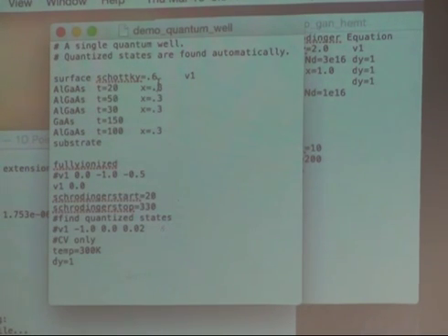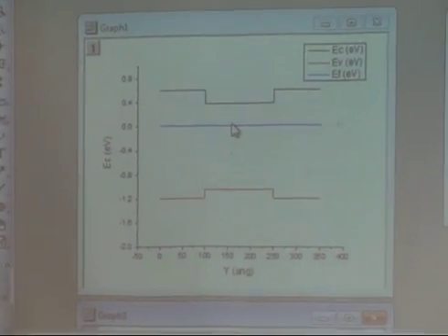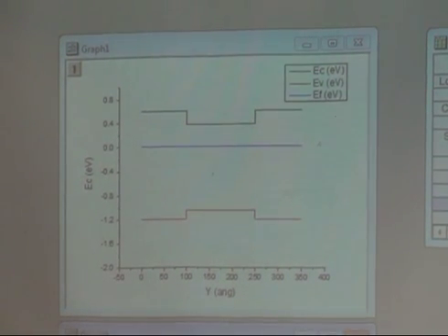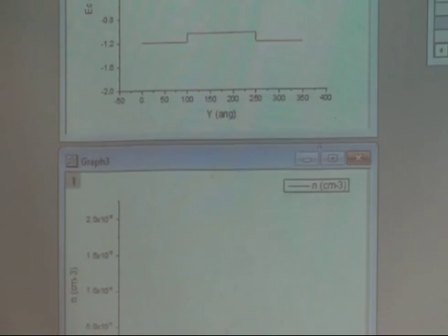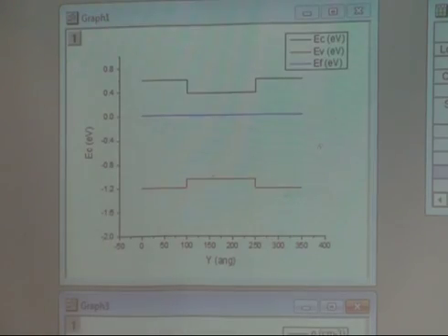What I'm going to do is populate that quantum well with electrons. Right now, you look at this structure, there are very few electrons in the quantum well. I mean, there are some, of course, but they're exponentially small, and the carrier density is very low. Right? I want to put electron gas into that quantum well, and that will be the channel for the transistor.